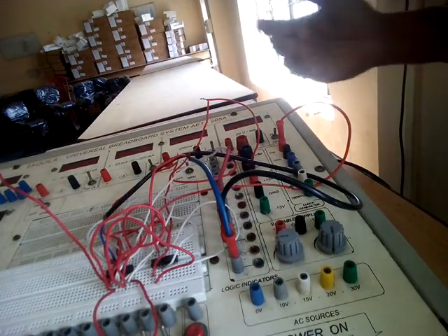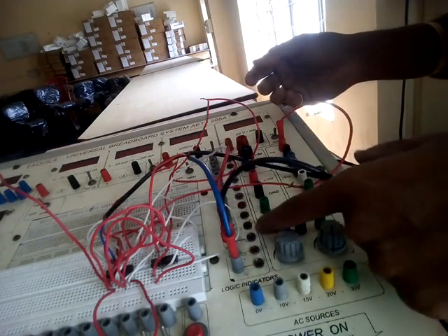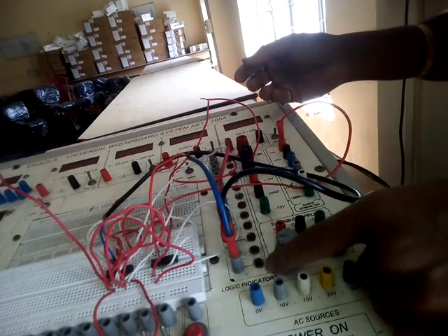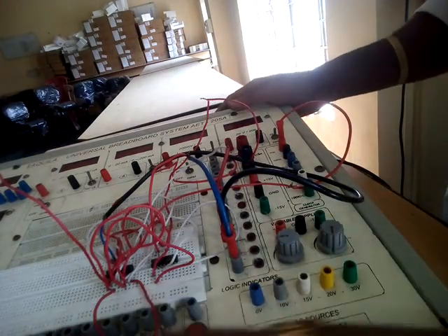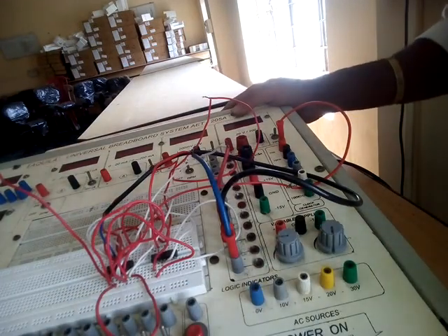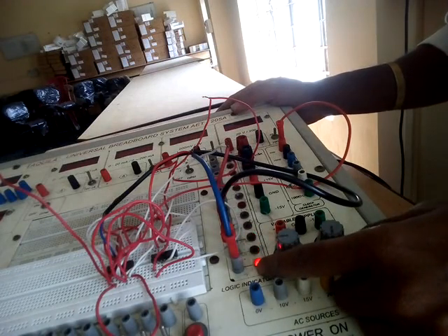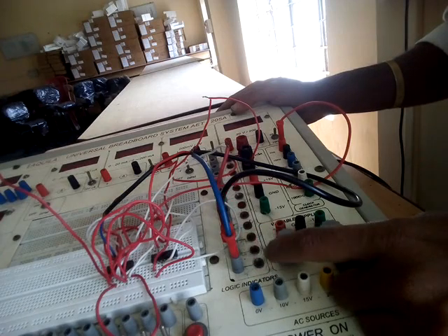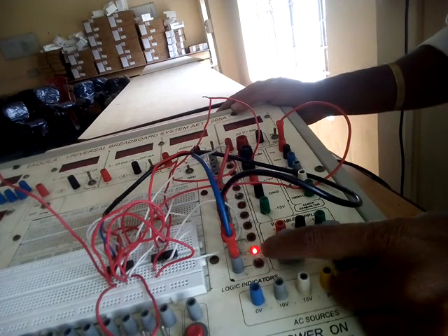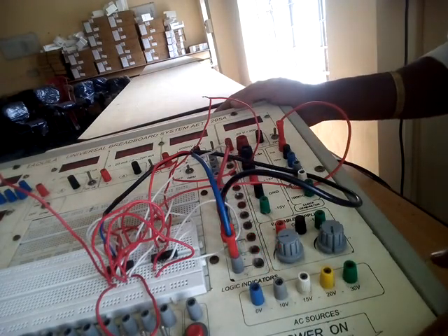So what we saw in the previous state, that is 000, 001, 010, now we see starting from 111. If CLR is made high, you can see this down counter: 111, then 110, 101. You can see it is a 3-bit asynchronous down counter.